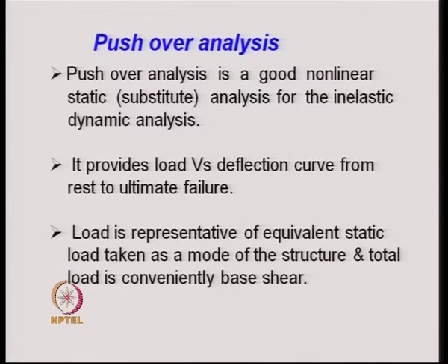In fact, the way the response spectrum method of analysis is a very good equivalent in static load analysis for earthquake forces, in the same fashion, the pushover analysis is a very good nonlinear static analysis for the inelastic dynamic analysis for earthquake forces.